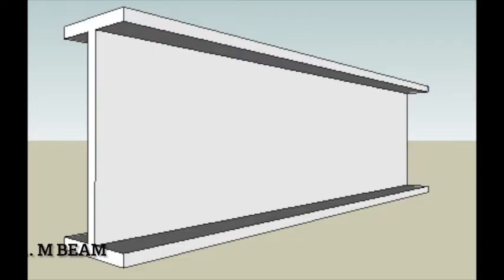M shape. A hot rolled structural steel shape similar to but not classified as W shape, designated by the prefix M followed by the size and weight of the member. So, a miscellaneous beam or M-beam provides an exceptional low weight per foot hot-rolled solution, primarily used in the frames of manufactured homes and recreational vehicles. This product is also utilized in purlin applications and for steel dunnage.